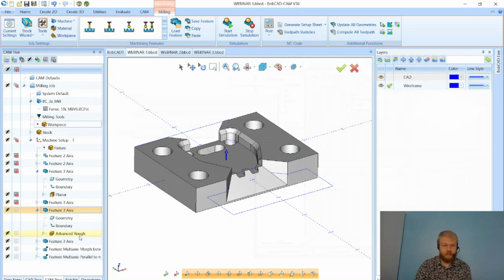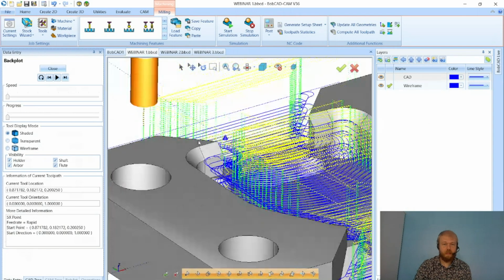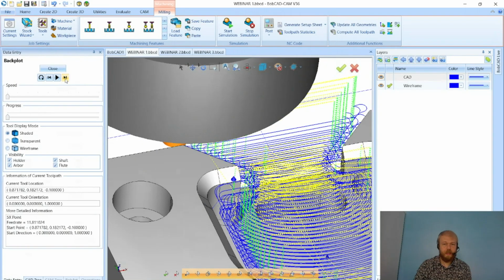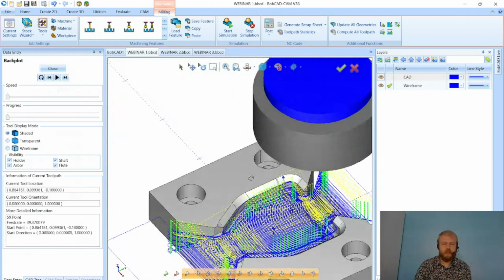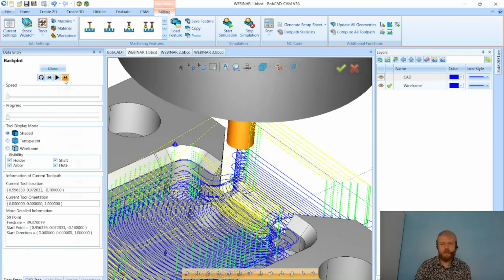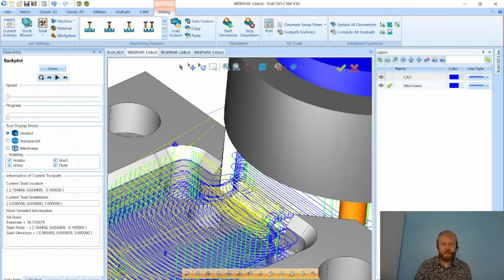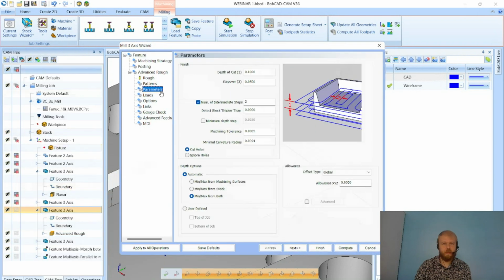You can see that tool path now. And if I backplot, you can see it starts from the outside of the stock and works its way in. The only thing at the moment with this toolpath, however, is with the different depths here with the holes and the slot, it doesn't give us any toolpath down in those depths, only because BobCAD understands there's no opening to the sides of them. So that's why I started with just a plunge operation with this.